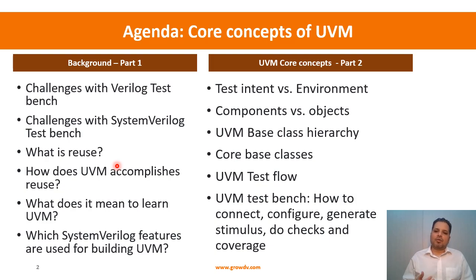And that is important because when you know how things have come, how things were, and how things have progressed, you tend to better appreciate and understand why UVM is doing it in certain ways, right? So that is the motivation. So we will just understand quickly what sort of challenges we faced when we built the Verilog Testbench, what sort of challenges we have seen with the SystemVerilog Testbench. Challenges means not the understanding of concepts, but where are they lagging, right? So why did it move from Verilog to SystemVerilog, and where does the SystemVerilog Testbench stand, and what is it that it is not able to satisfy?